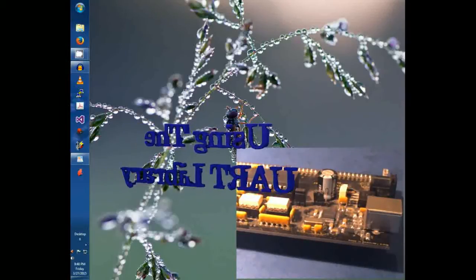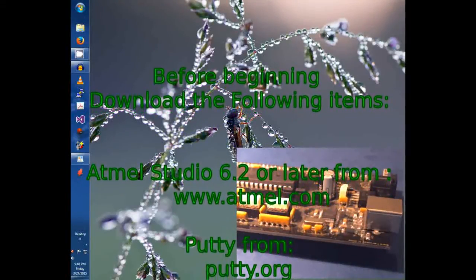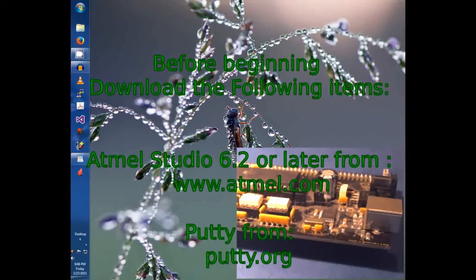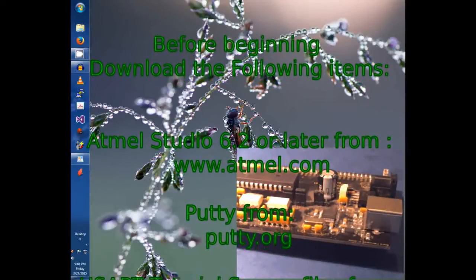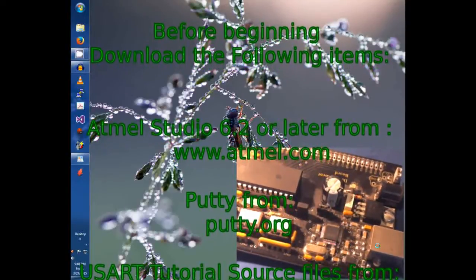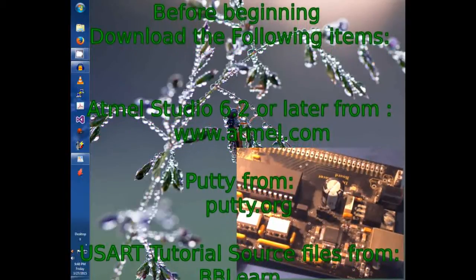This tutorial will show you how to configure your microcontroller development board to communicate with a terminal program using the UART library provided. The development board uses a 2-channel USB device to communicate with the host PC. Channel A is dedicated to downloading the program to the microcontroller.